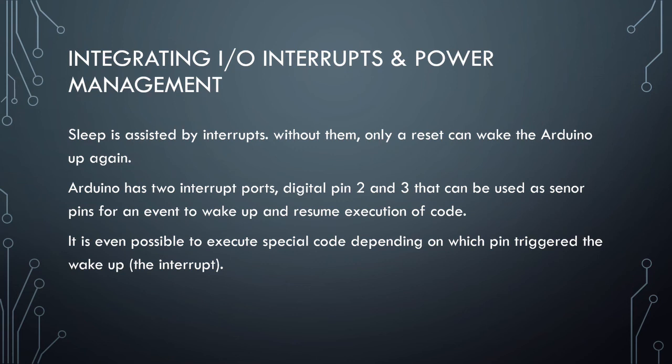So for example, this Arduino board that's really comparable has two pins, not dedicated, but one of their functions can be used for an interrupt port. We can even integrate special code depending on which pin triggered the wake up. If it is pin 2, one thing could happen. If it's pin 3, something else could happen when you trigger the wake up. So we have a couple different options.